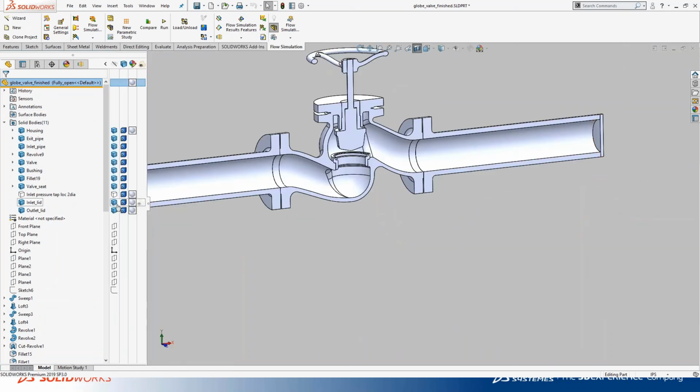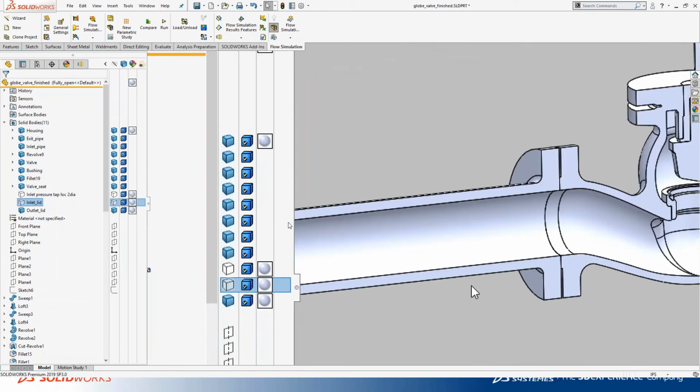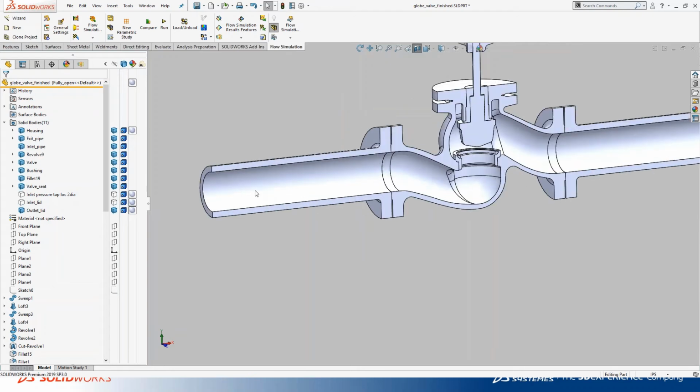Let me show you what this was previous to that, which is how it was presented, with the opening, as we want the flow to move through that. And very simply, you can add geometry, a simple extrusion from a converted sketch of that pipe diameter, and just extrude that out very easily, and that very easily caps it off and makes it watertight.